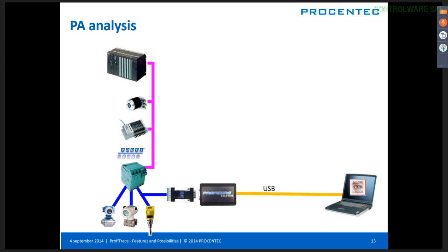If we want to use Profibus PA, we can just add a PA probe. So we need our standard Proficore, but we can add a PA probe to that, and this PA probe will take care of this Manchester bus power communication. It's a very small design.